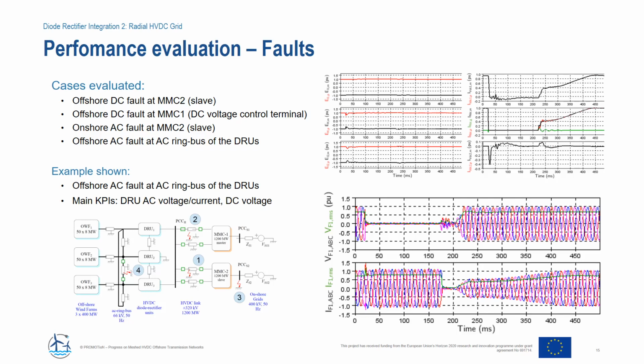During the fault, wind power plant AC voltage decreased to 0 PU and wind turbine currents reach their limits. When the fault is cleared, the wind turbine controllers ensure a smooth system recovery.